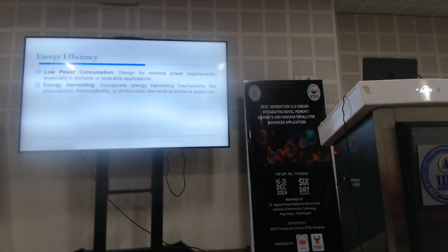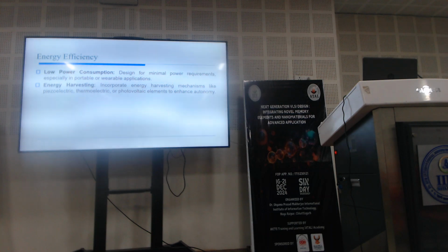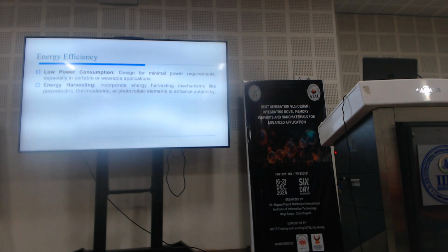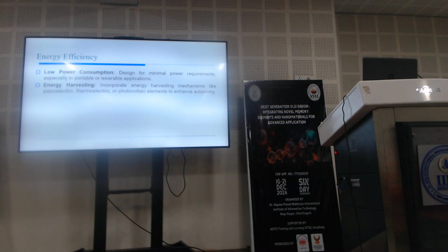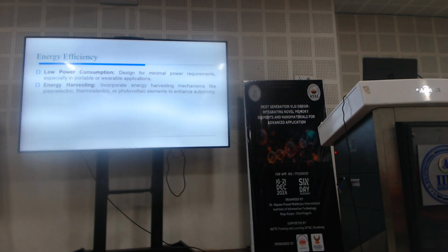And the next one is energy harvesting. That comes in forms like piezoelectric, thermoelectric and photoelectric. Whenever we convert from mechanical sensors, for example, force, we can convert it into an electrical form in two ways. One is with the help of a change in capacitance, or we can use a piezo material to get the electrical value directly. Capacitance is passive in nature, whereas directly using piezo is active mode. We can consider both principles.